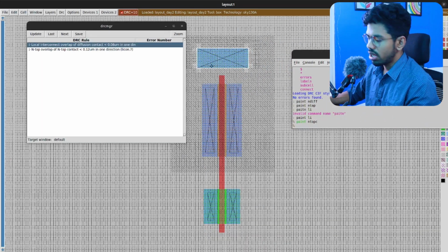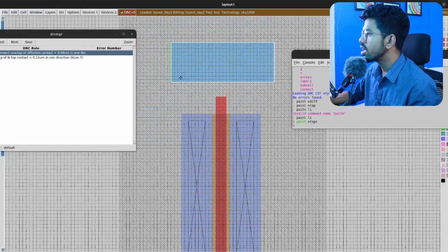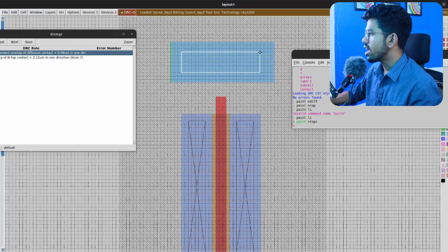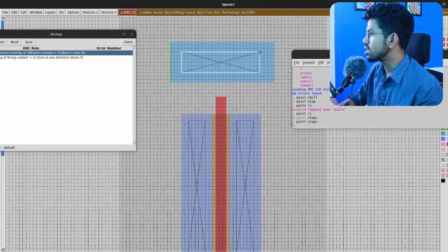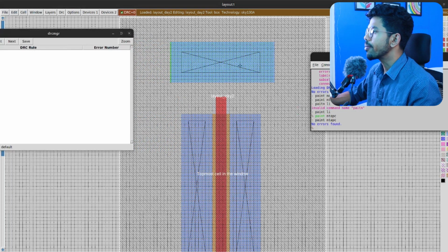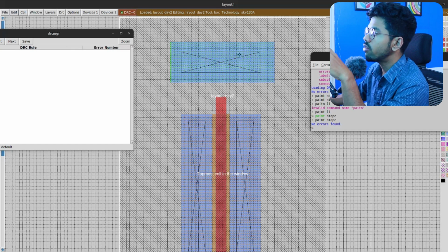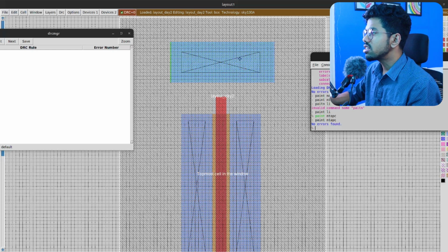So let me zoom in, go up, and here I will select a smaller area like this to avoid the DRC, and then I'll write paint N tap C. And great, I think there is no DRC now, it is DRC clean. But one thing here: in the physical world, we don't draw only one connection. One connection means a bigger hole will be created. Instead of a big via, we insert a few small vias, like 3 small vias, but for now it's okay, let it be.